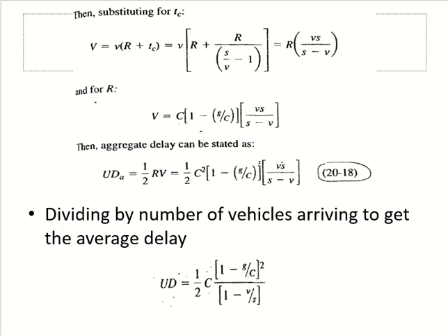Okay. Now in this equation we have V by S, which again looks very simple, right? Which we don't like. We'll change it. V is the demand, the flow rate coming. S is the saturation flow rate. Instead of saturation flow rate, we want capacity here.